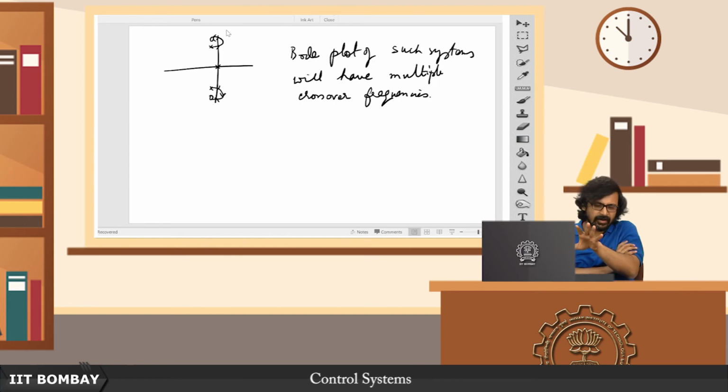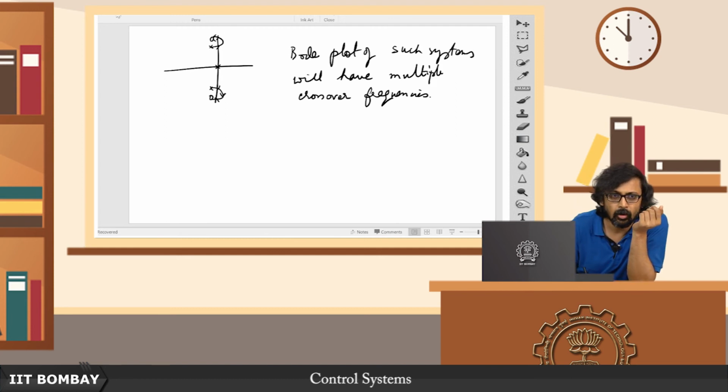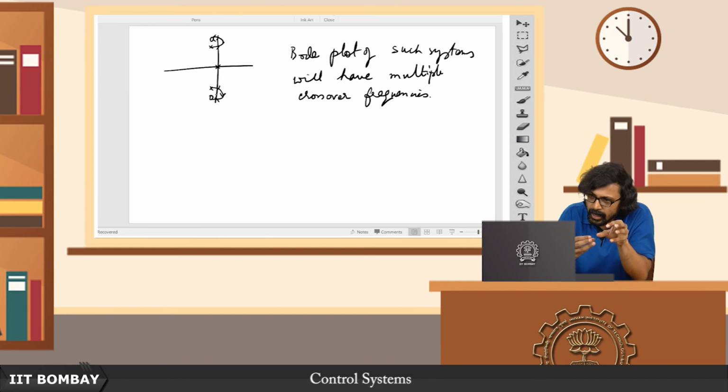In general, it is very true that a positive gain margin and a positive phase margin for an open loop stable system is desirable. But what if you already started with a gain such as this, which means that you had already taken your open loop stable system and increased its gain such that the closed loop system was becoming unstable, and then someone left the knob over there and you did not know this.